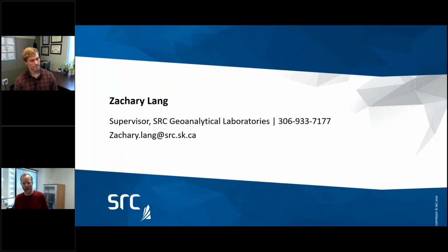Okay, great. So somebody asked about the relative costs, both in CapEx and OpEx, of dense media separation versus XRT. Okay, good question. There are a few considerations in there. Sensor-based sorters can be very expensive and can be limited by your size ratio. They become a lot more cost effective when you can use them in coarse sizes, so 10 to 30, 30 to 90, where you can get a lot more capacity.